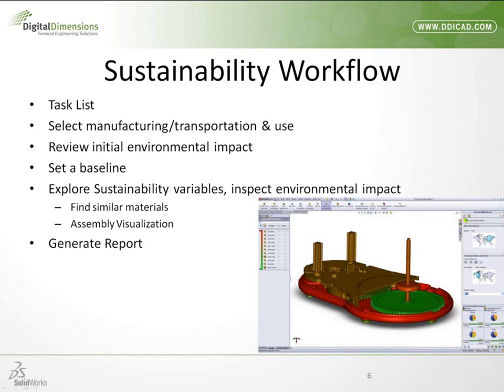Now with sustainability, there is a database set that we've gotten from PE International, and we have all the applicable information from a database that we can apply these environmental studies with. Now, if you've selected a material that doesn't comply with that, sustainability will bring up this task list and will allow you to select a different or similar material to go about your sustainability study. So we will show you that task list.